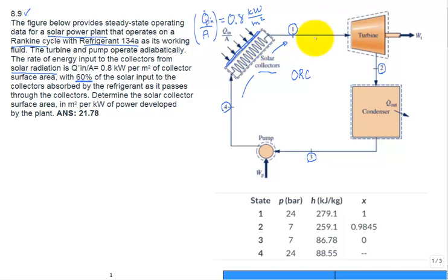Okay, so from 1 to 2 you go through the turbine, we understand that. From 2 to 3 you go through the condenser, you're rejecting heat, and right away we have a little complexity coming out of thermo 1. If I have a little control volume, that's what they're showing here for this turbine, then W dot T is positive out of that turbine. Great.